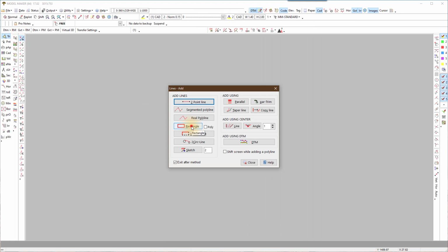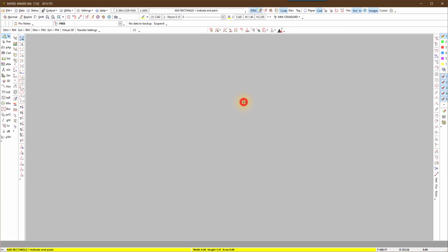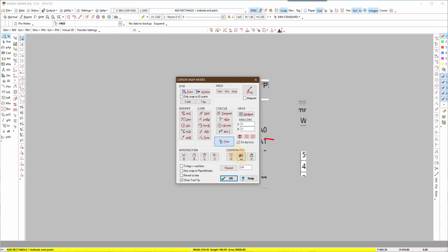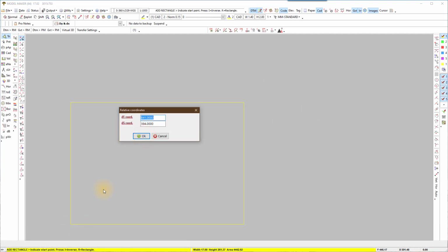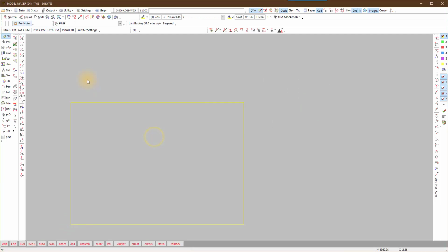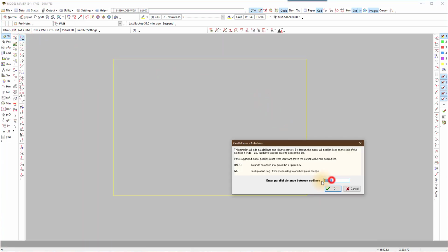Draw a CAD layout or import an existing CAD drawing of a title block. First I draw an A1 title block to illustrate the process if you do not have an existing CAD drawing of a title block. Confirm that the size is correct. Draw the frame inside the paper edge. In this case I make it 15.